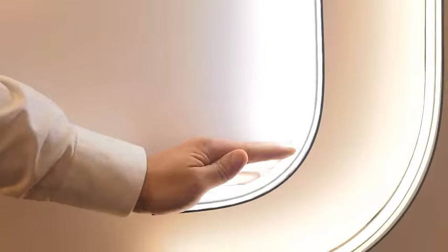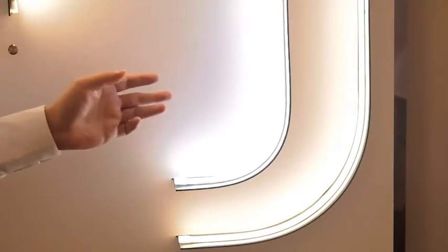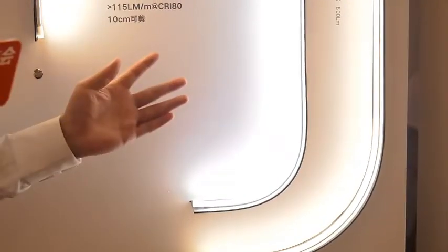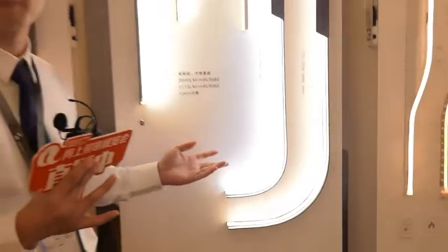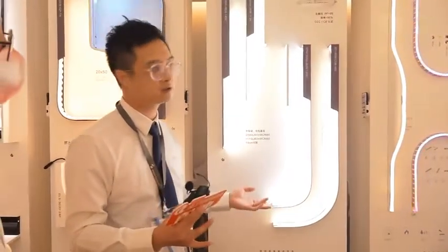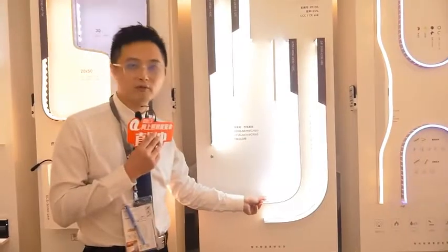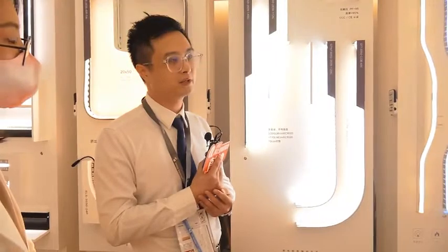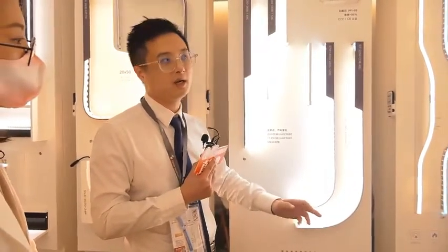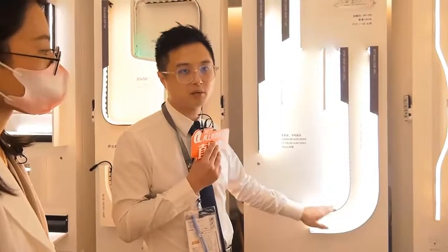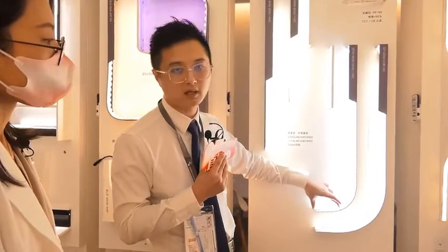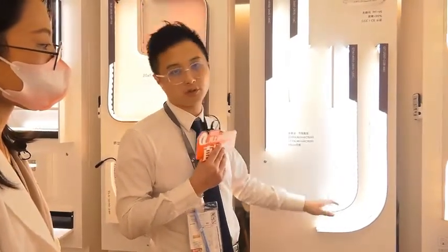And this is the best choice for projects, for contractors. Normal high voltage strip can be cut each meter or maybe half meter. But this one we can cut in 10 centimeter. It's a lot shorter. So when the contractors are installing the strip lights, it is easier. They can cut in 10 centimeter, and they can reduce the cost, reduce the loss.